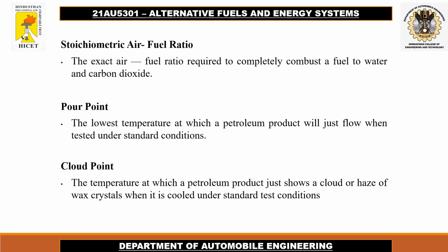Stoichiometric air fuel ratio. The exact air and fuel ratio required to completely combust a fuel to water and carbon dioxide. Next important property is pour point and cloud point. Pour point is the lowest temperature at which a petroleum product will just flow when tested under standard conditions.